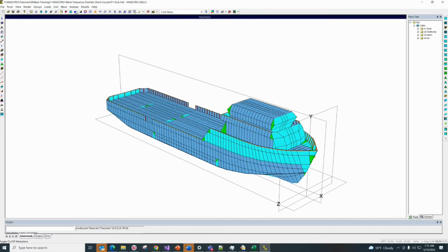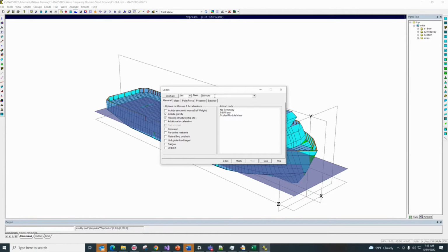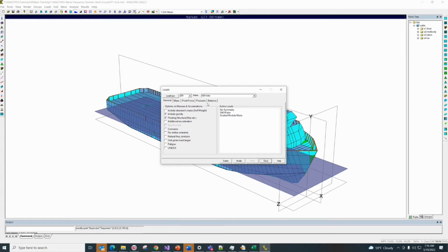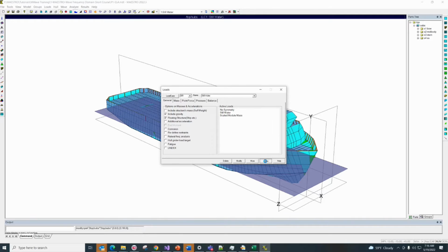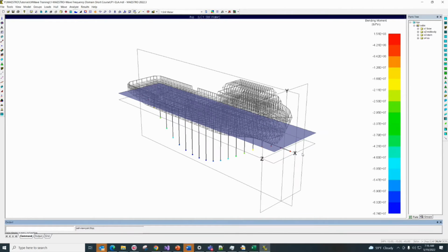We need the mean surface line to run the hydrodynamics. After your rotation, you probably do the rebalance for the inertial base. So the first load case, we call this the hydrodynamic load case 1. If you want to relate to the SML file, that's your inertial base code. In this case, there's a scaled mass, module scaled mass, everything takes the same mass, and there's a floating hydrostatic buoyancy. So you want to make sure it's balanced. Okay. You usually check the bending moment. It's in equilibrium, right? Bending moment starts at 0, ends with 0. So now you say, okay, I can run the hydrodynamic.